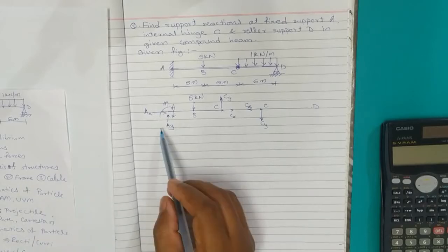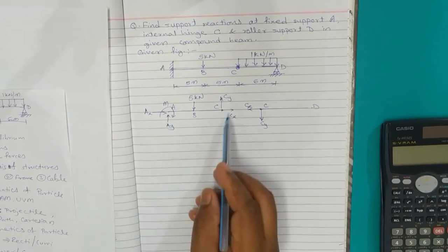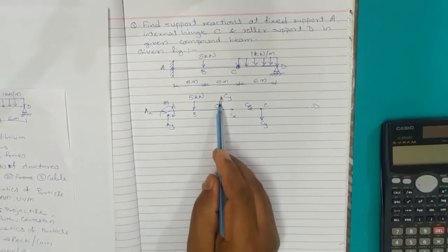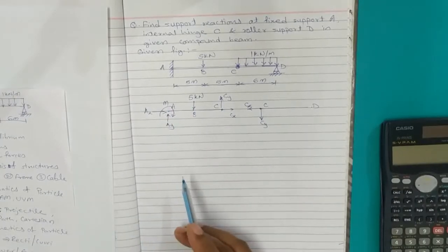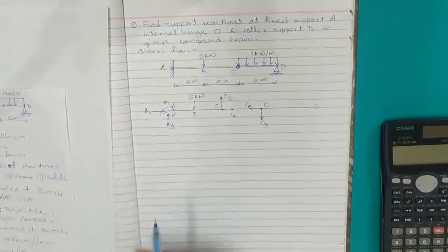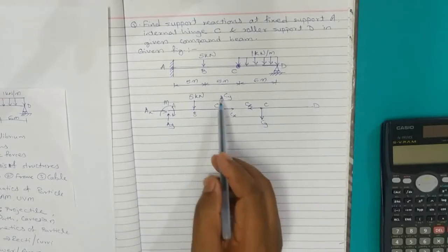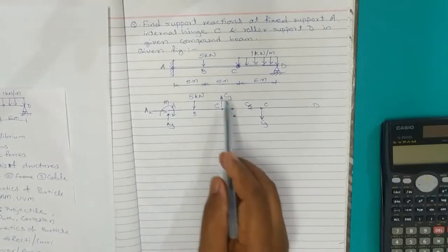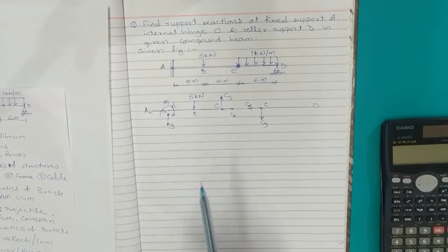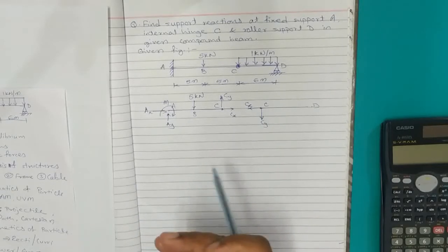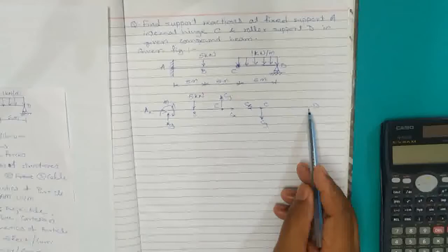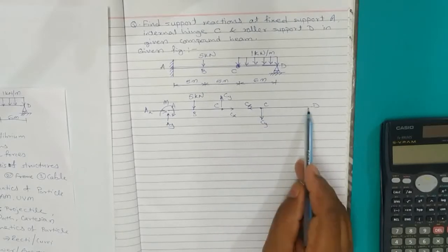Fine. Now here we can see how many unknowns there are in the FBD of the part AC: Ax, Ay, moment, Cx and Cy. In all there are 5 unknowns, whereas for solving any non-concurrent system in equilibrium, we have only 3 conditions of equilibrium. So we cannot solve this FBD of the member AC in the beginning itself, because that is not going to be convenient. We are not going to have all the unknowns solved using only 3 conditions of equilibrium where there are 5 unknowns.